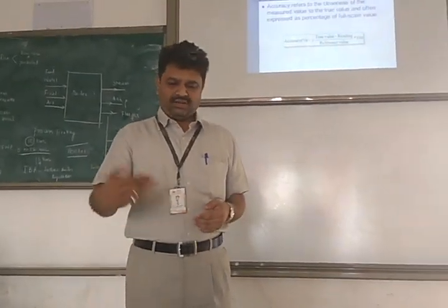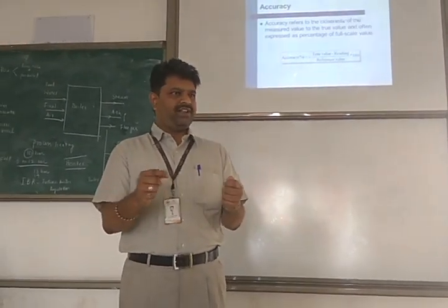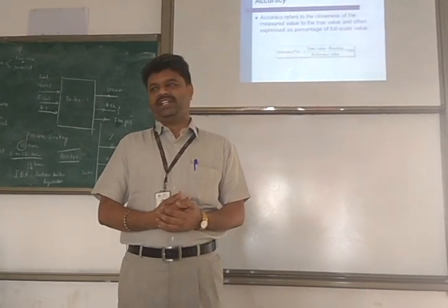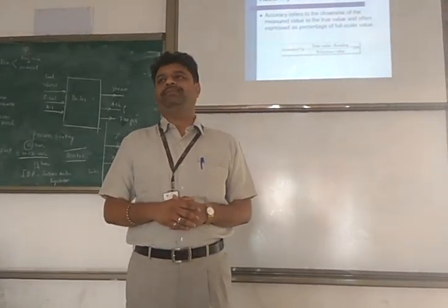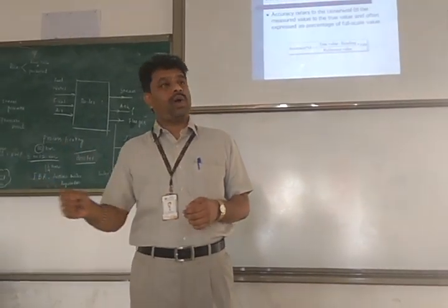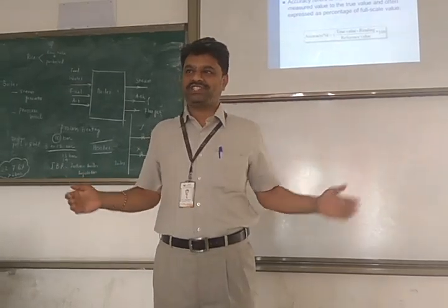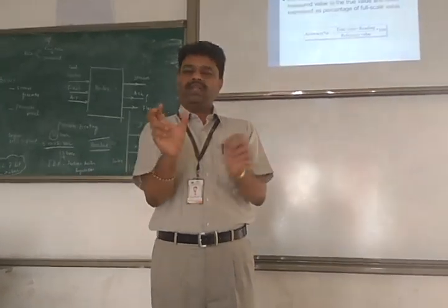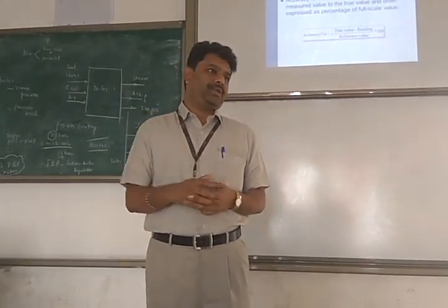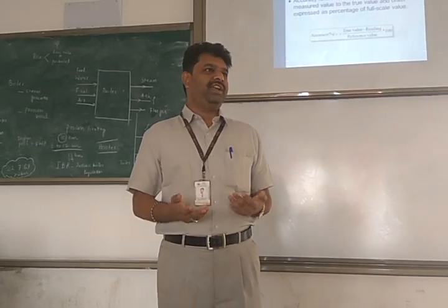Whereas you go for a little better instrument. You will go for a micrometer or vernier caliper, something like that, 0.01, 0.001 accuracy. You will get it somewhere around 5,000 rupees, 6,000 rupees. Some more better instrument, if you want to go to 0.001, then you have to go for an electron microscope or some other sophisticated instrument to measure the same distance, or the same width or thickness of the object. You have an optical projector to measure that. That will be around 5 lakh rupees. Electron microscope, maybe 15 lakh rupees, something.